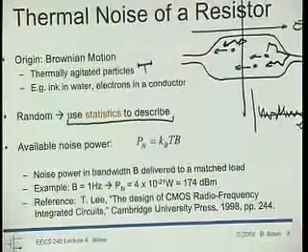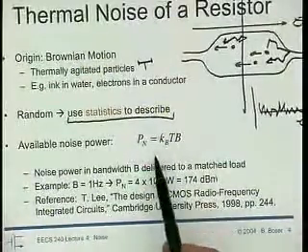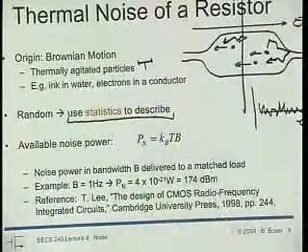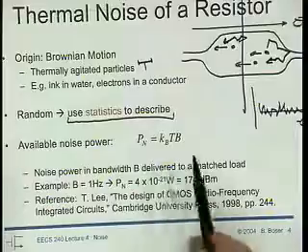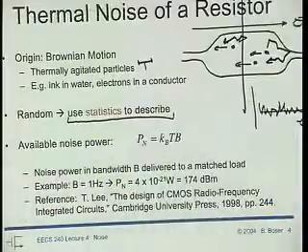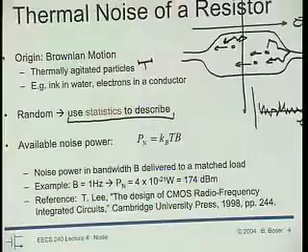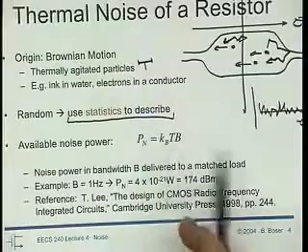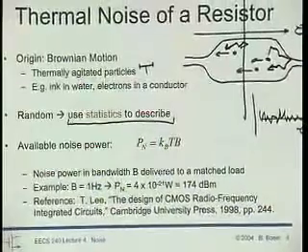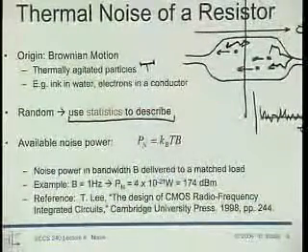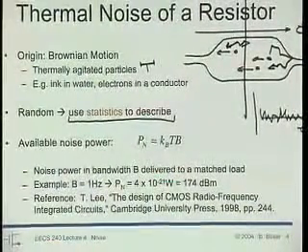And then there comes this thing that is usually referred to as the equipartition principle, that says that really the noise available per degree of freedom is kT times the bandwidth. Noise is distributed over frequency, right? And so the wider a band we have, the more noise we get.